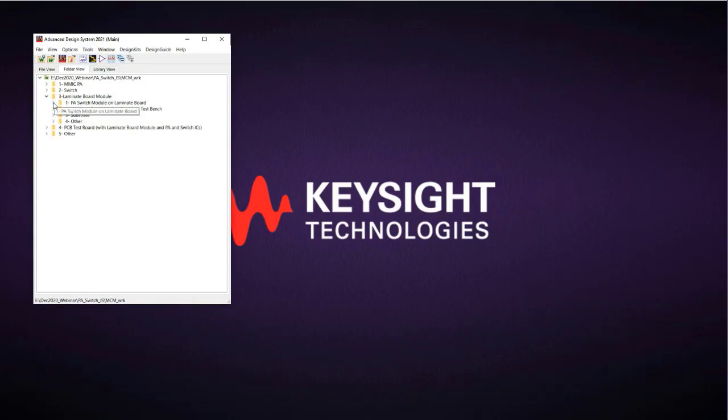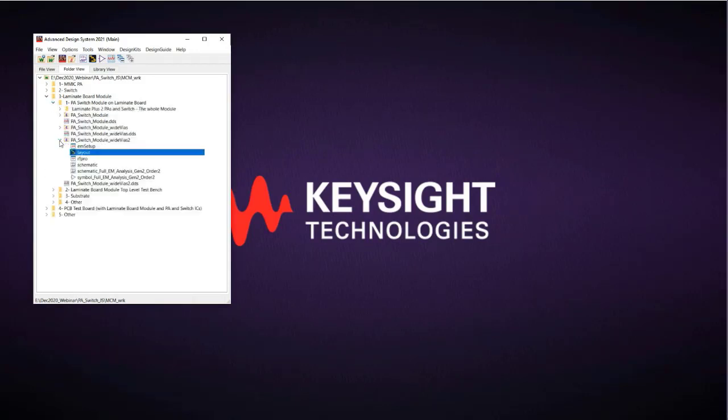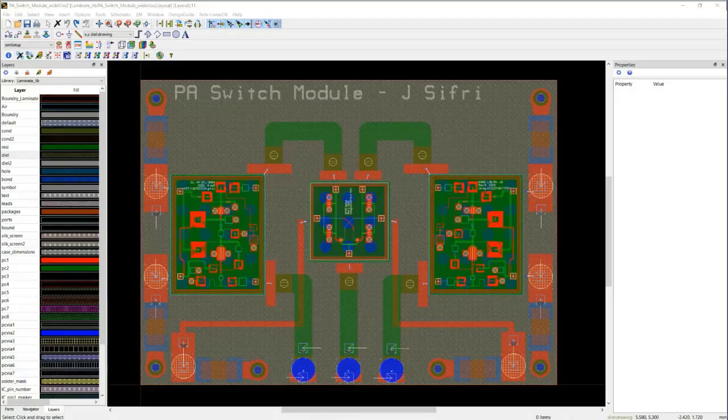Okay, now let's move to the next level of assembly in folder 3. As you see, I have dragged and dropped the three ICs onto a laminate board. The scaling and layer mapping of the two technologies, the MMIC and the board technologies, are done automatically with Smart Mount. This is the layout of the module with the laminate board and three ICs assembled face up onto the PC2 layer.